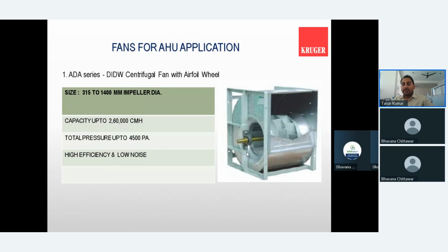So always when our static pressure is more than 50 mm, we should preferably go with either the backward curve fan or the aerofoil curve fan. That again depends upon your efficiency requirement. Whereas the forward curve can generate less static pressure, up to 50 mm static, and for lesser efficiency we are using the forward curve fan.